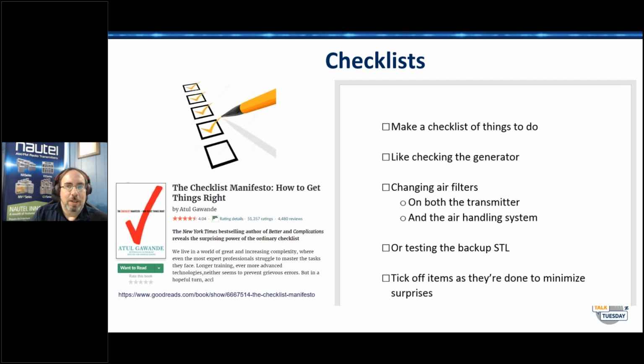And I'll take that a step further and go with stainless steel or copper wool instead of regular steel wool. Real good stainless steel, 4/0 steel wool, and then pump it full of spray foam. And then if the spray foam's on the outside, spray it with a little bit of spray paint so the sun doesn't eat it up. And if it's a really tiny crevice, fill it full of silicone caulk, the good elastomeric caulk. But if you have any light that you can see in that building that's coming from outside, a mouse can get in there, or a roach, or something you don't want.